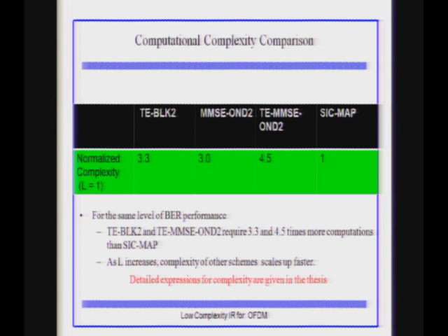If you are talking about very fast adders, we have to have carry look-ahead, and then you need more silicon area. It scales up even with the number of bits that you use. An 11-bit multiplier and an 11-bit adder, working at more or less the same speed, I would say 20 times more complex. The multiplier is 22 times more complex than an adder of the same bit width.